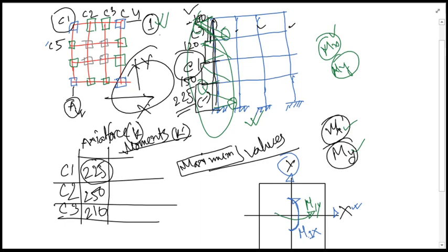If we are drawing the one frame, then obviously we are drawing the diagram when the wind load or the lateral load is acting upon this plan view, as you can see from this direction. So if the lateral force is acting parallel to the x-axis in this direction, then the bending will be occurring within this C column. That will be called the M1y. So the moment value you'll be obtaining from this will be M1y.